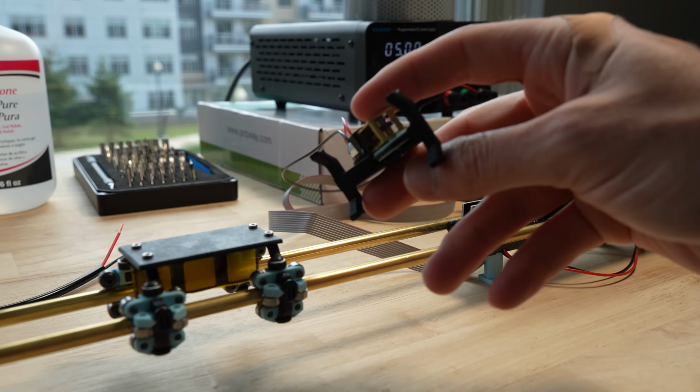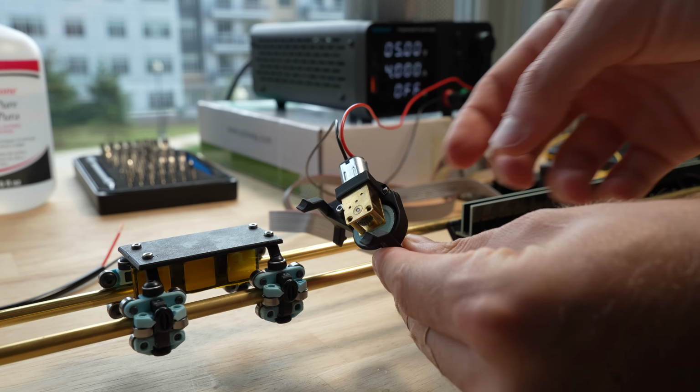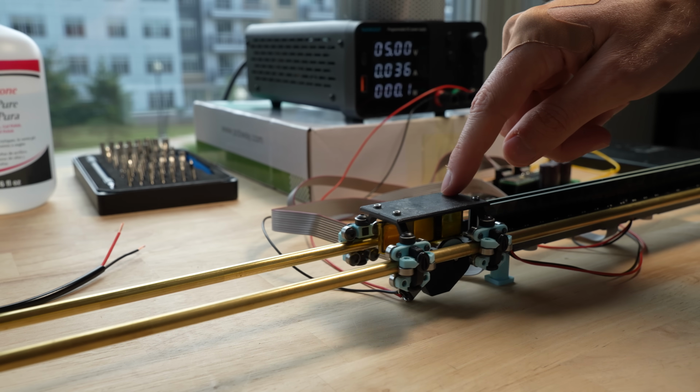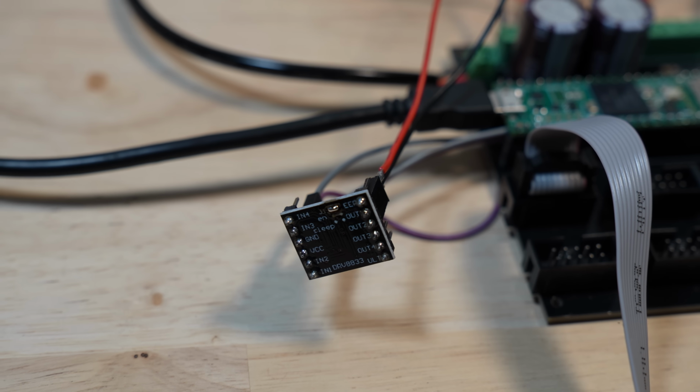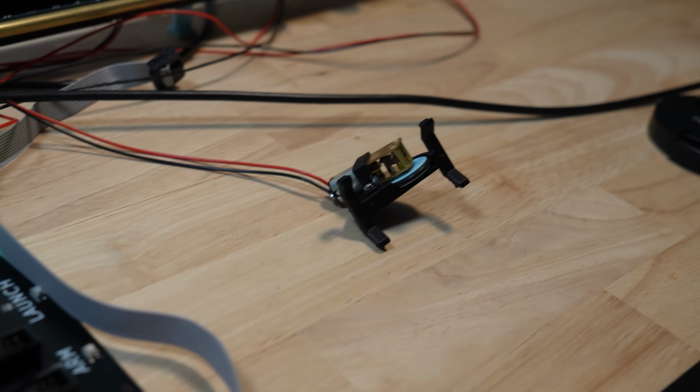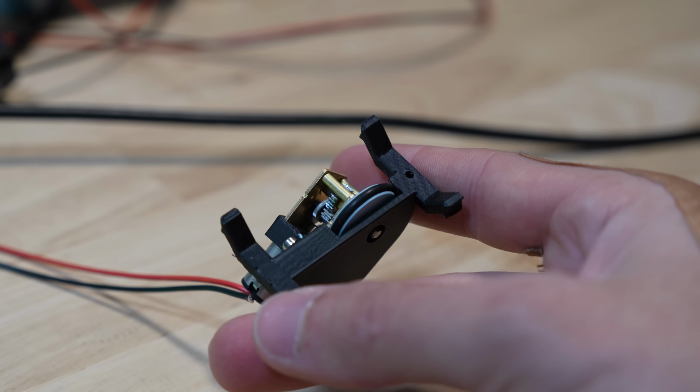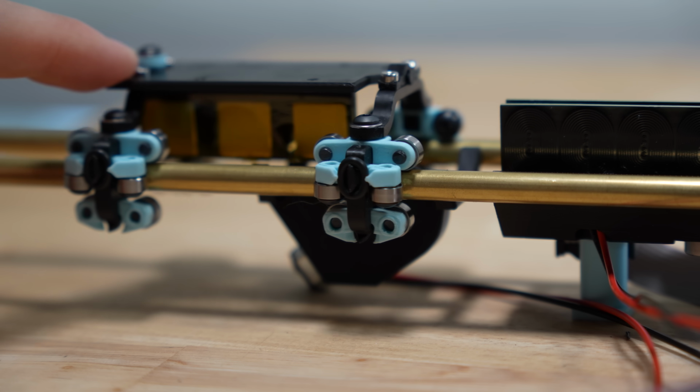Next up, I added some drive wheels. These are good for positioning trains at lower speed before they actually launch, like to align it with the launch segment. Unfortunately, I forgot that motor drivers are kind of needed for this, and I don't have any on my control board, so I soldered on this little doodad. And that, kids, is why you should always break out some extra pins on your custom control boards.